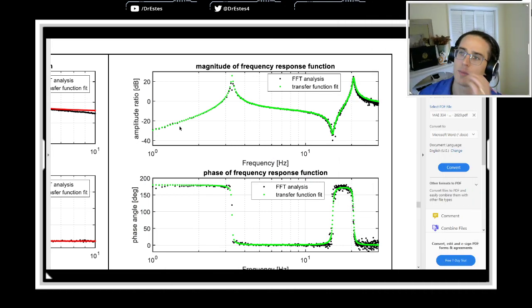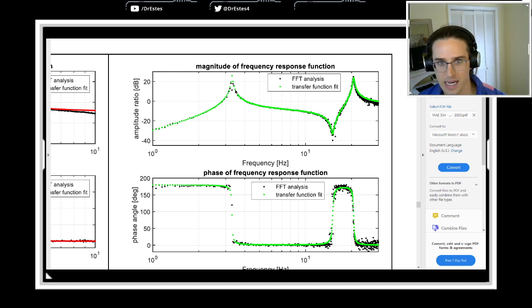If you're a structural engineer designing a helicopter or an aircraft, and let's say this models the structural vibrations of a wing, you want to make sure that if you have a peak like this, that during flight, you never encounter a condition where this frequency would be excited. It's okay to have peaks in your response as long as you never see those frequencies in practice. Otherwise, it could be catastrophic.